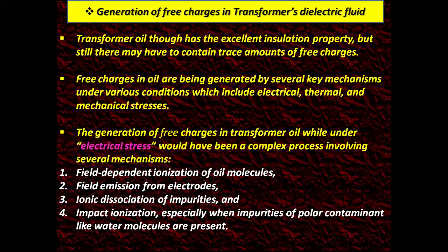Let's start with generation of free charges in transformer's dielectric fluid. Transformer oil, though it has excellent insulation property, may still contain trace amounts of free charges. Free charges in oil are generated by several key mechanisms under various conditions, which include electrical, thermal, and mechanical stresses.